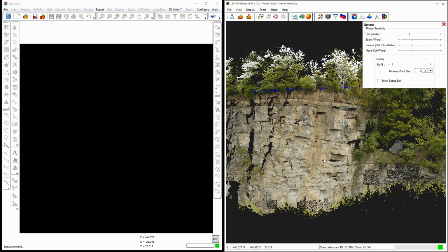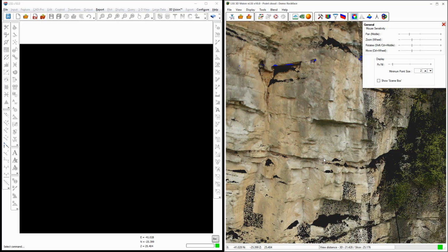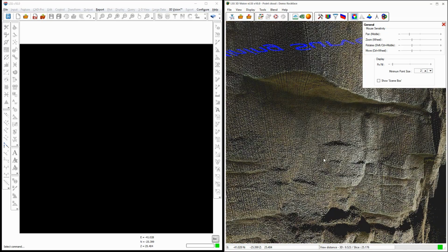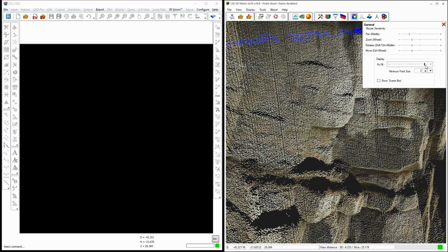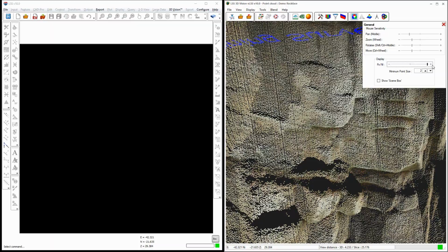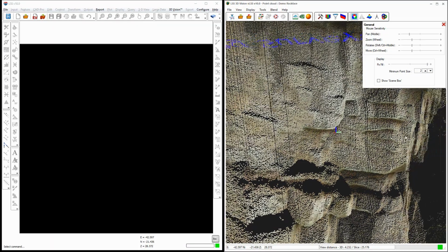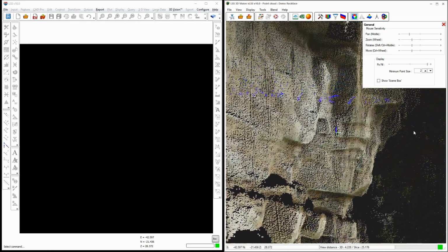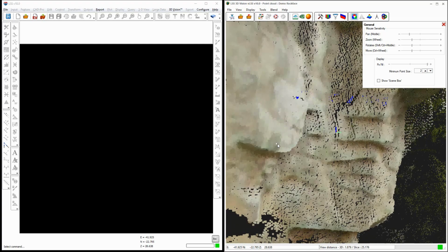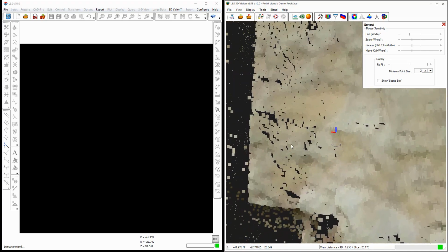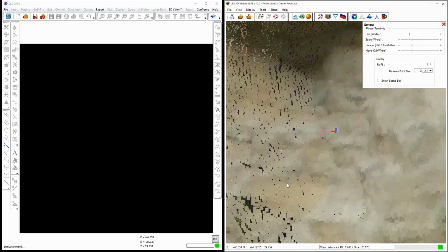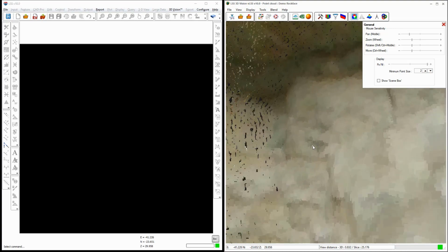And in those situations where the gap between the scanned points is leaving a bit of a gap, you can set pixel fill on, and for points that are close to the eye they will get bigger. It won't affect points further away, but it means that as you get closer to them they will fill the gap, so that you have a solid colour shading there rather than small dots with gaps between them.